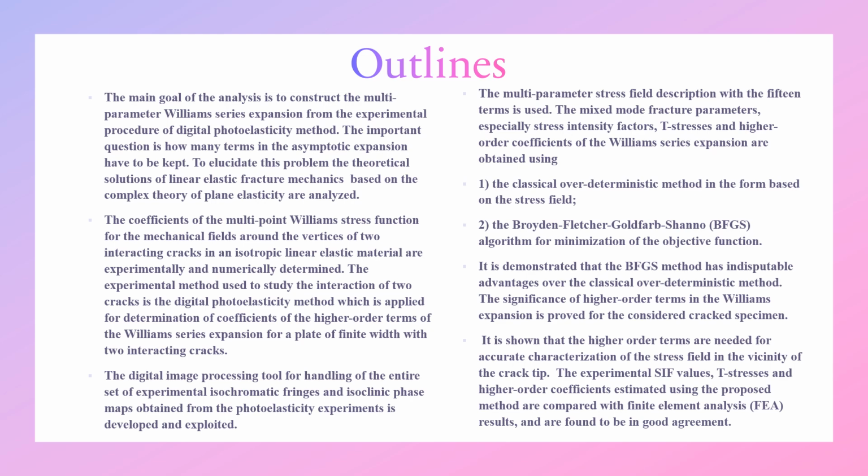To elucidate this problem, the theoretical solutions of linear elastic fracture mechanics based on the complex theory of plane elasticity are analyzed. Based on this analysis, the coefficients of the multi-parameter Williams stress function for the mechanical fields around the crack tips of two interacting cracks in an isotropic linear elastic material are experimentally and numerically determined.